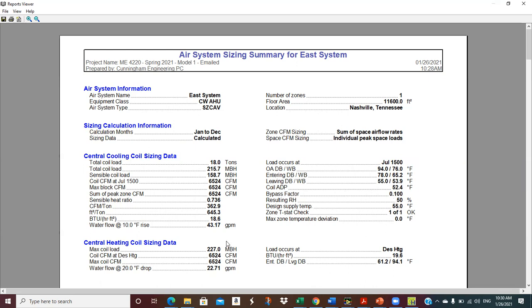And so you can see it'll give you CFM per, let's see, I'm sorry, square feet per ton. Some of these numbers are what you look at to see if you pass some sanity checks. That's actually a lot of square feet per ton of cooling, 645. So when I saw that, that would perk my ears a little bit. I would typically want to see that number down, you know, 400 or 500, something like that.